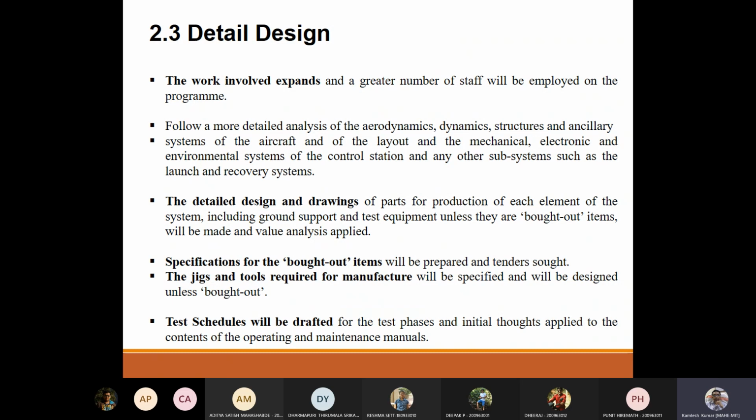Then environment related pressure, temperature variations, velocity. What is the feasibility, is there a possibility to test that? We have to test. Moment of inertia, CG, all those things should get captured. Then during the test itself, you should have all the detailed documents for each component, testing details as well as operating details, and how to do the maintenance.